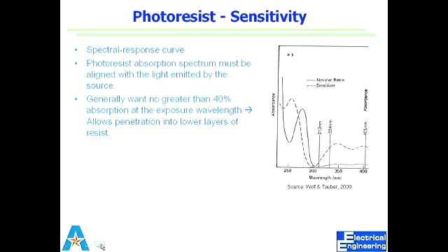So that sensitizer is what's going to change the response of that resist to that wavelength. So it can become absorbent at 350. Yeah, so it's different depending on the sensitizer, right? Because that is going to cause absorption now in that film. Once it gets absorbed, you have that energy available to get your reaction done.